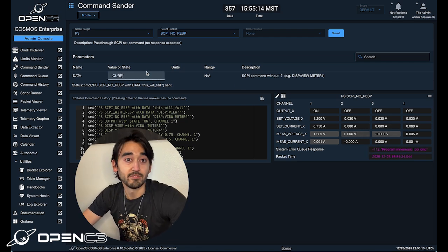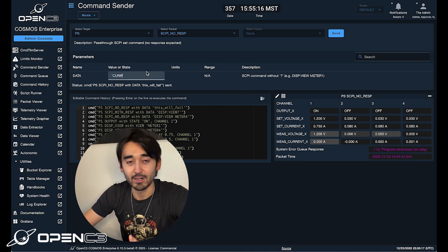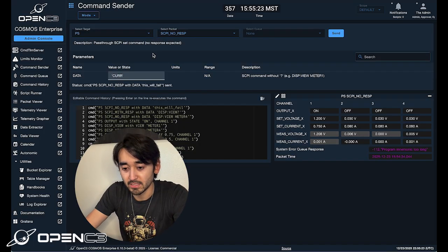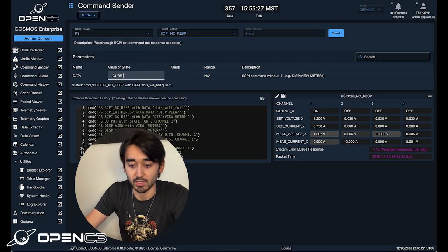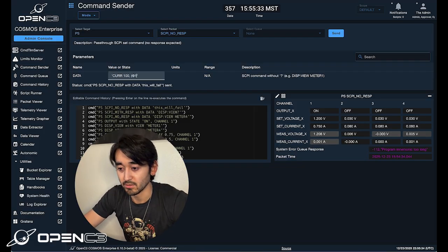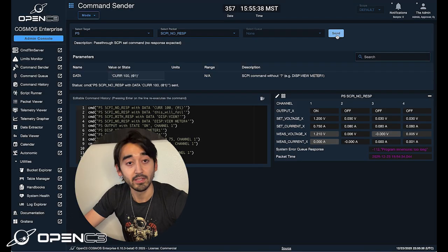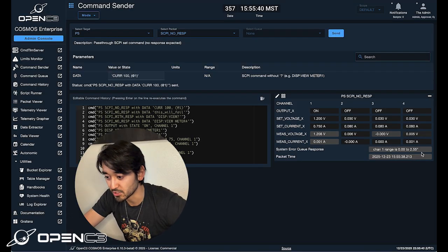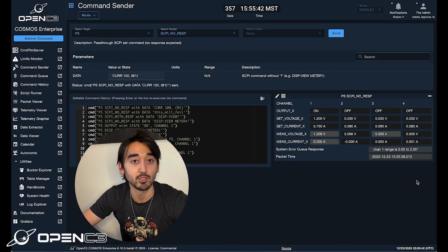So obviously that was going to fail. That was never going to work. So let's say we are trying something and there's some kind of legitimate error that might be happening. So maybe that is current. I want to set the current to 100, which is going to be out of range of channel 1. So I'm going to try to send that out and see what happens. And we get a new error message back. So the message is channel 1 range is 0 to 2.55.